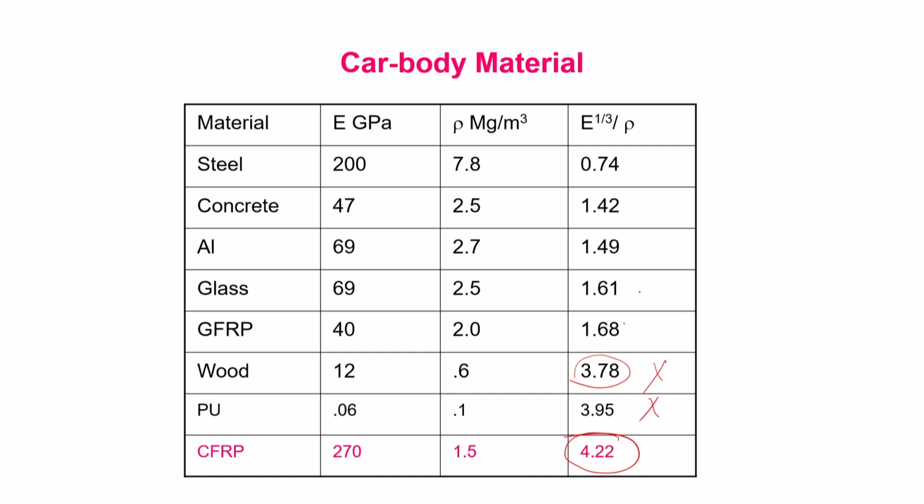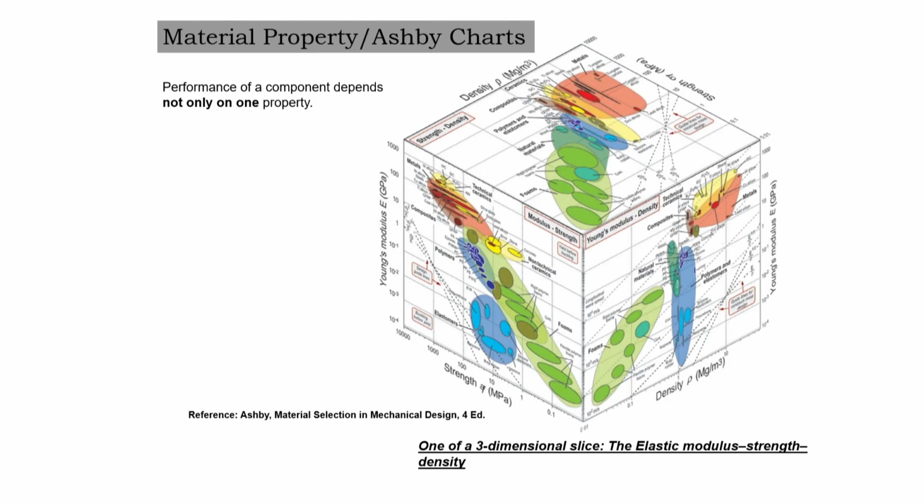So, glass, no, it is bad in terms of compressive strength, okay, bad in compression. So, we cannot utilize it. Now, we can see that aluminum and steel are the 2 competitors, and out of this aluminum is a better choice. In fact, we can actually get an Ashby chart like this, and in this chart right now we are looking at only, Ashby chart can be multi-dimensional.